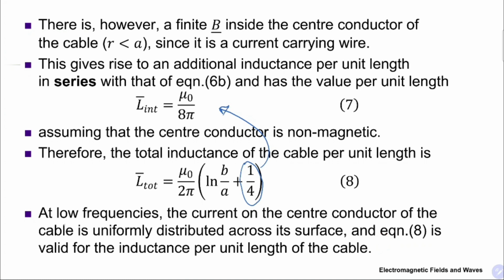Okay, so this is for low frequency, because at low frequency, the current is uniformly distributed across the inner conductor. At high frequency, this is no longer the case, because the current is actually just on the surface of the conductor.